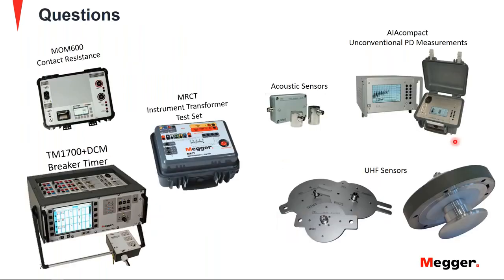Our first question I'll direct towards Daniel. Daniel, what is the recommended method for demagnetizing CTs? Thank you, Michael. Well, the preferred method is the AC method. A unit like the MRCT can go to 2000 volts AC, so it would slowly ramp it down to demagnetize the core. But it is also capable of using a DC method, where it will start from a value typically the same as what was used for the testing, and then slowly go down, reversing polarity, doing several different passes, again reducing the amplitude and changing the polarity. But the preferred method is using AC, which the MRCT can do.